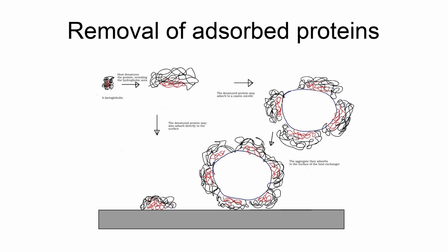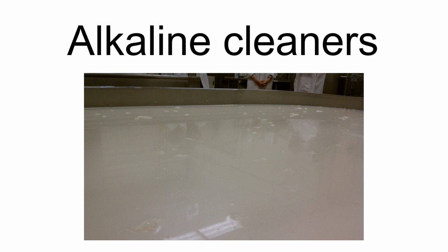An example of a strong alkaline cleaning agent is sodium hydroxide, also called caustic soda. Although sodium hydroxide, NaOH, can cause corrosion on food contact surfaces such as stainless steel, it is the preferred cleaning agent for protein removal due to its efficacy in dissolving proteins and dispersing and emulsifying food soils. Silicates are often added to these cleaners to reduce corrosion on metal surfaces.